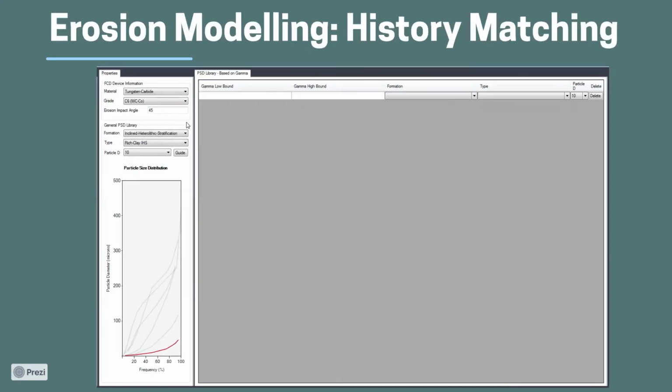Another important factor in all these production designs, especially once you go into aggressive environments like thermal operations, is erosion, because we're always dealing with sands, and these sands come into our production. It also affects our history matching that I previously mentioned, but it also impacts erosion and eroding our facilities and our FCDs, our pipes. So we have to have a capability of running this inside our software. There are a few softwares dealing with erosion, but all of those are droplets. They are not handling the erosion of the sand.